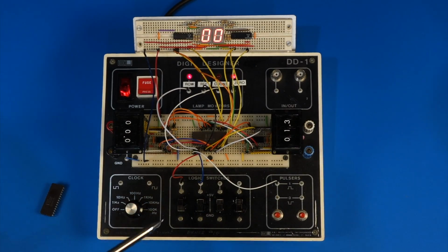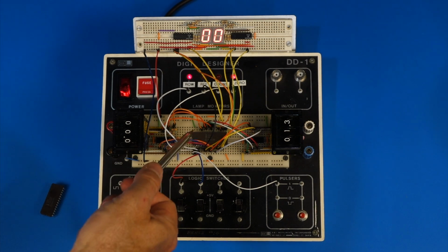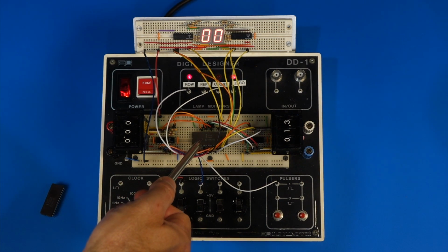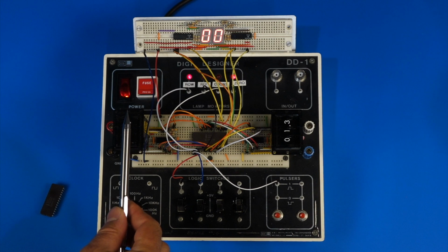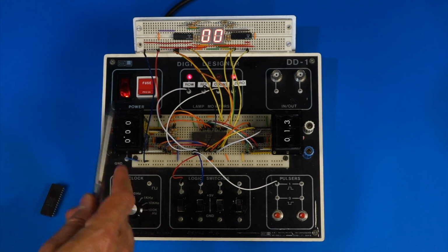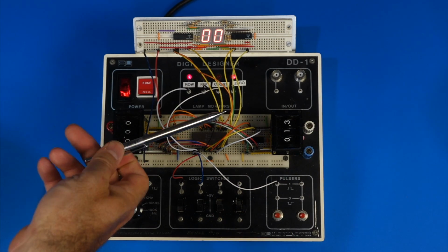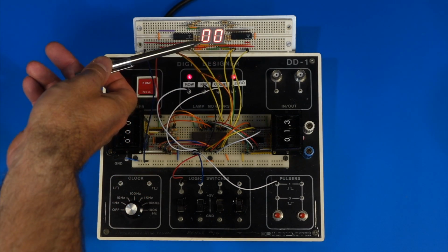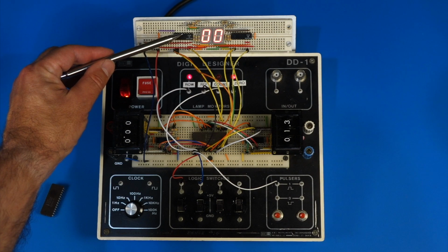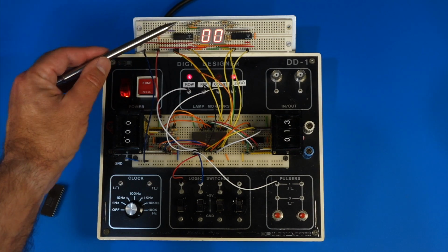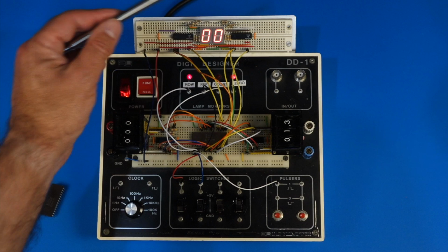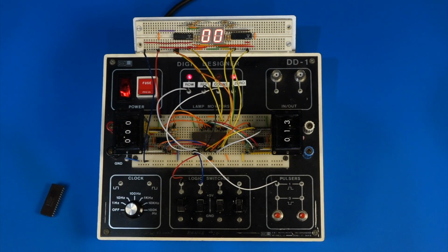So I went ahead and built a little demonstrator for the Intel DRAM controller chip. So I now have 6 bits of input for the row address on these wheels, 6 bits of input for the column address, and I'm reading the multiplex output also on 6 bits. Those are simply BCD to 7 segment decoders and 3 bits each. So it's all in octal, by the way.